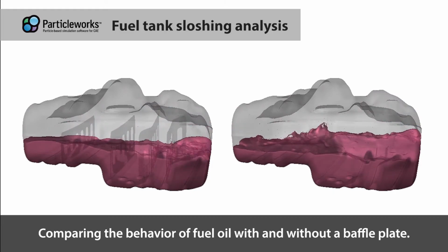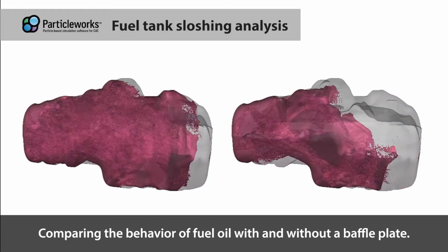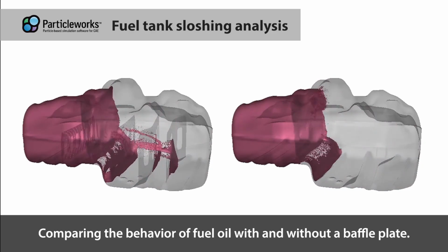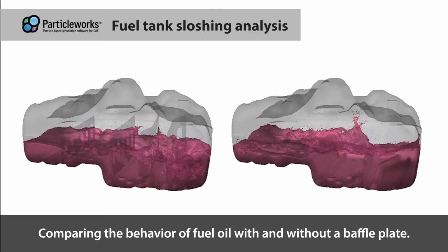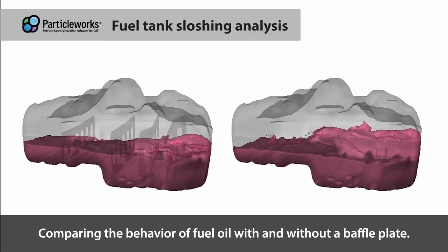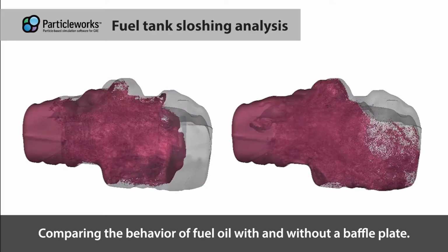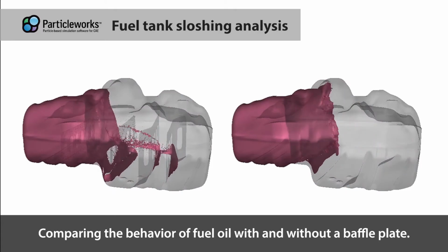Fuel tank sloshing analysis. We are simulating the oil behavior in the fuel tank while the vehicle is running by applying an external acceleration force. The oil behaviors with and without a baffle plate can be compared to evaluate different design effects.